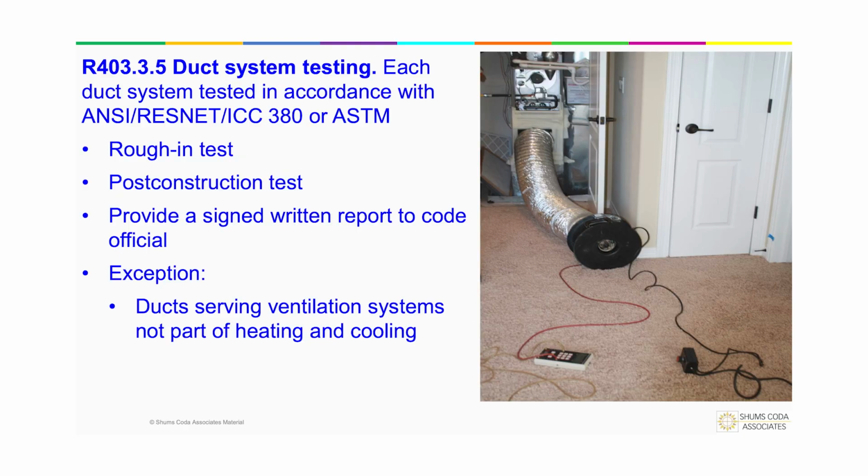All right. Now, here is something that is incredibly important to realize. We have testing criteria. You are required to test your ductwork. You have options. You can do it at rough-in. You can do it at post-construction. The choice is all yours. The only thing is we do have to have a report provided to the code official that says I do not exceed the numbers that we're going to talk about here very shortly.